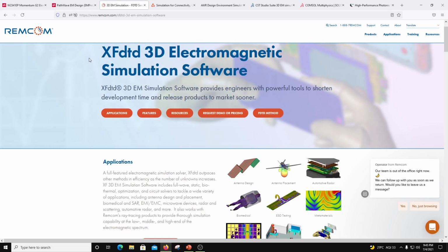Antennas are simulated in a small box, and once you do the simulation, all the surfaces of the boundaries of the box are where the near fields are totally absorbed, or numerically they are not reflecting back in, right? Once you do that, you will be able to transform that near field information into what you call the far field through a certain transformation. So that's how the antenna patterns are computed. It's not that the entire space is discretized up to a far field region. No, they are computed in the near field and then a transformation is applied. That's how antenna patterns are computed.